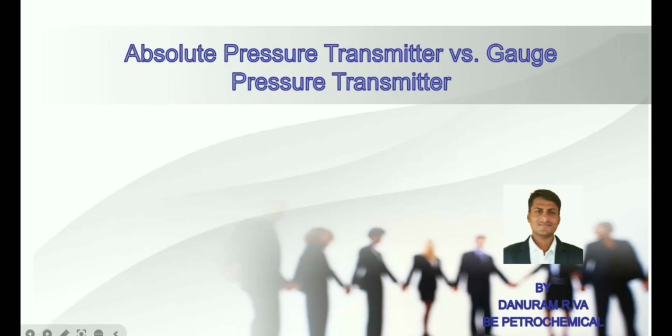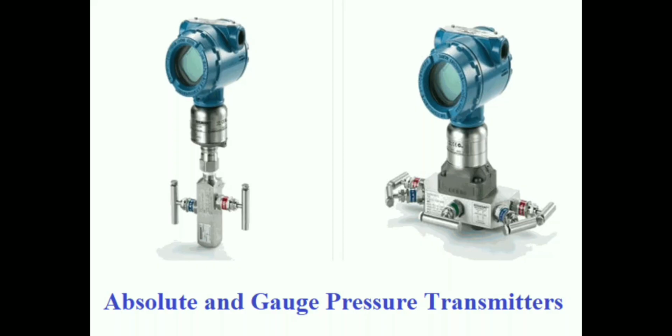In this video, we are going to see the difference between an absolute pressure transmitter versus a gauge pressure transmitter. First, let us look at the definitions of both transmitters. An absolute pressure transmitter measures pressure relative to an absolute vacuum, which is zero pressure. The reference point is a perfect vacuum. The gauge pressure transmitter measures pressure relative to atmospheric pressure. The reference point is the atmospheric pressure at the location of the measurement.